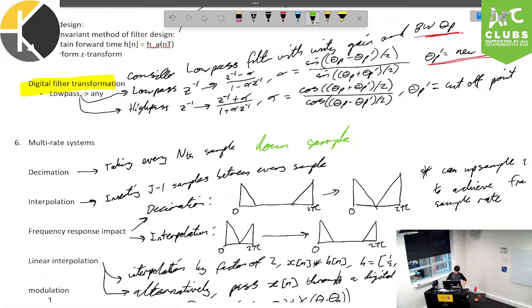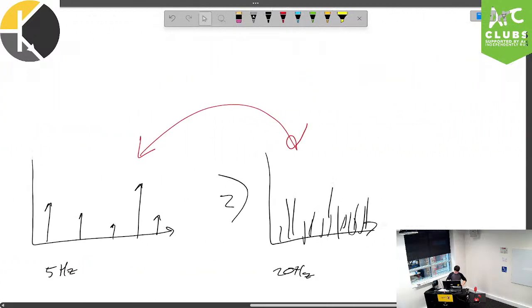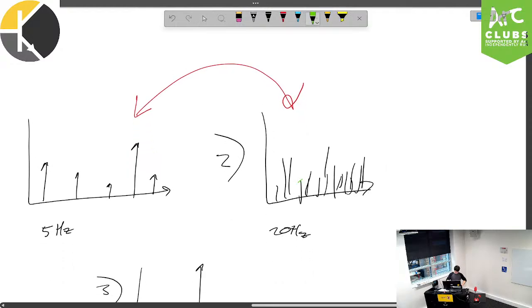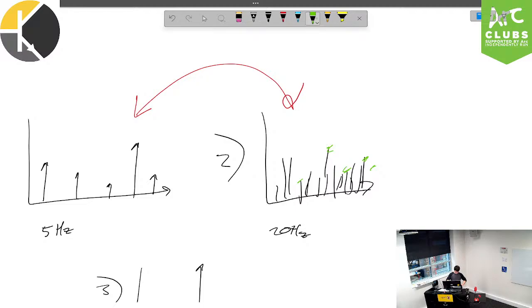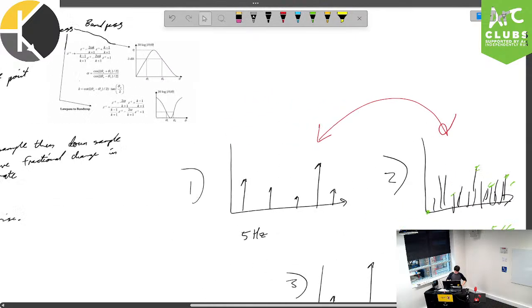Downsampling is typically referring to decimation. Decimation is where you just take the nth sample in every set, okay? And so by taking the nth sample, I can decimate by a factor of 4 in this instance and just grab every 4th one, okay? In which case, it reduces this to 5 hertz, in essence. Nothing too fancy with it, but that's that.